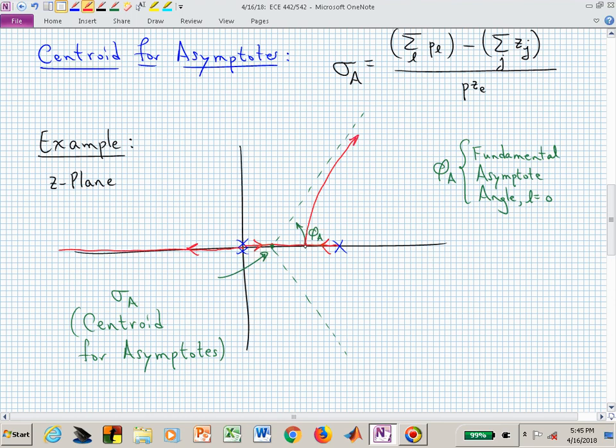This branch is going to go down. It's going to be symmetric. If we put a mirror on that real line, it would see the same thing above and below. And there are 3 branches of that root locus, and that's rule number 4. You wouldn't even have to compute the breakaway point. You could just eyeball it, unless I explicitly ask for it on the exam.